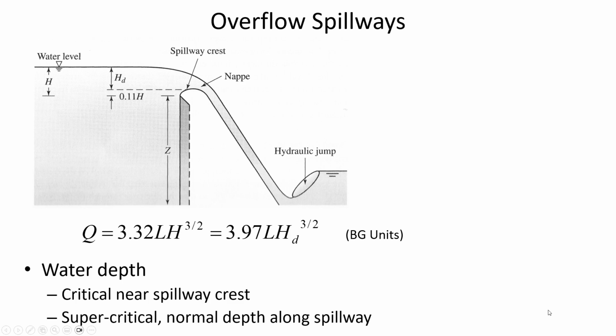All right, so we saw an equation in that video which was saying that the flow over a weir depends on the length of the weir, the height of the water above the weir, and then there are some factors which we wrap a couple of different terms into a discharge coefficient, and typically it would be the gravitational constant as well as a factor that talks about energy loss over the weir.